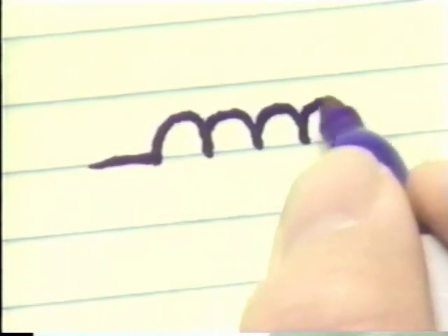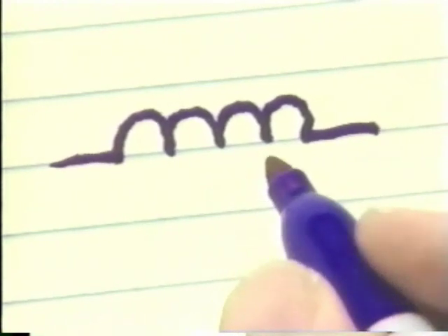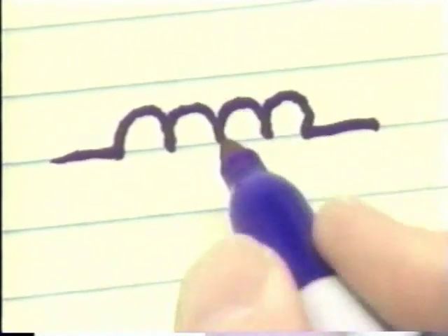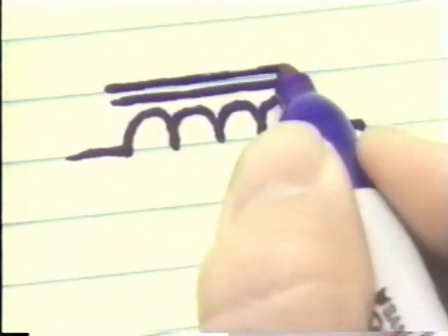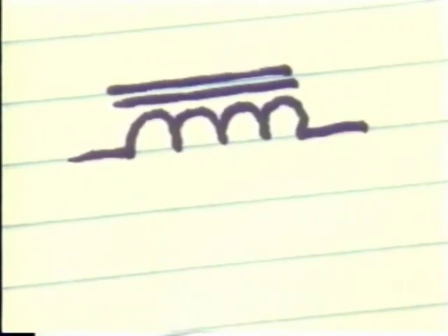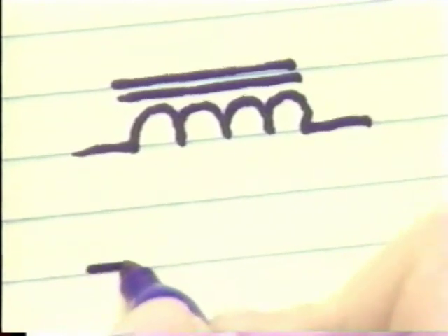Just as capacitors can have different types of dielectrics, inductors can have different types of cores. Don't forget that the strength of a magnetic field depends on the type of core material used. The type of inductor symbolized on the schematic so far has been for an air core inductor. Some applications require an iron core inductor, which is schematically represented by a coil symbol with two lines next to it indicating the presence of an iron core.